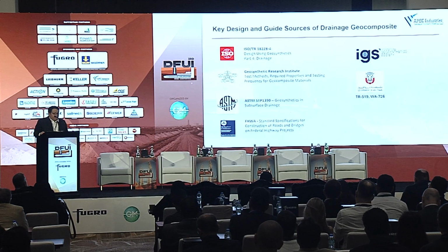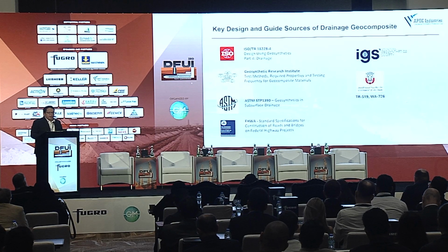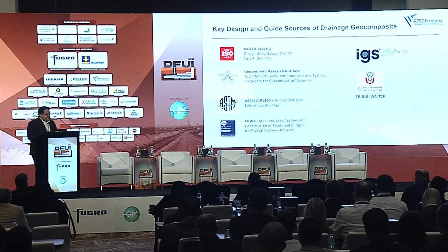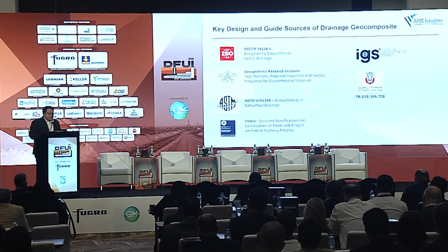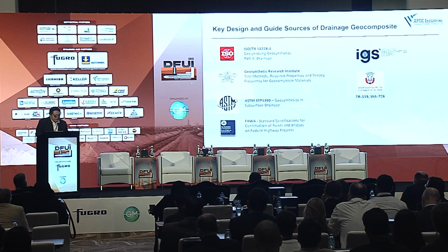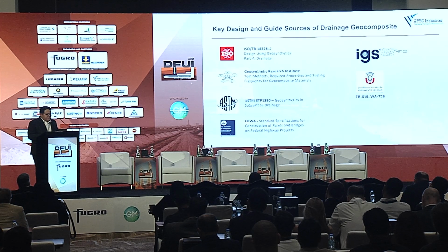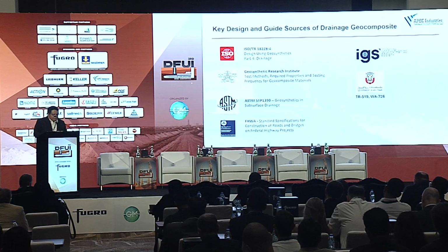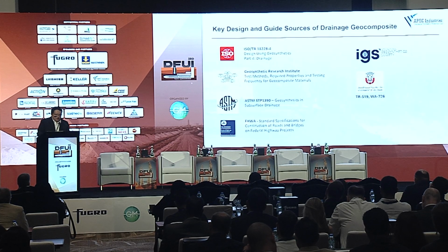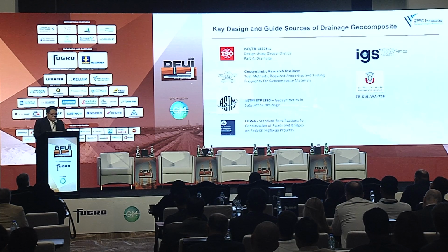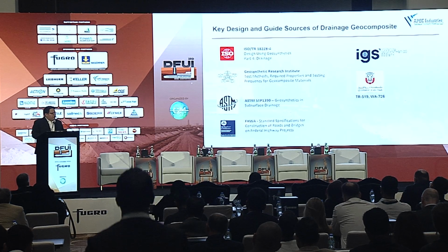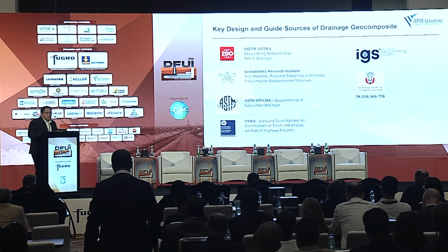The performance of these materials depends on several design parameters. This includes transmissivity, compressive strength, creep resistance, filtration compatibility, flow at different hydraulic gradients, and installation survivability. Long-term performance under confinement is especially important because the drainage capacity of these materials can change significantly under sustained loads. Therefore, a proper design should always consider the actual field conditions rather than the technical parameters of the material itself.